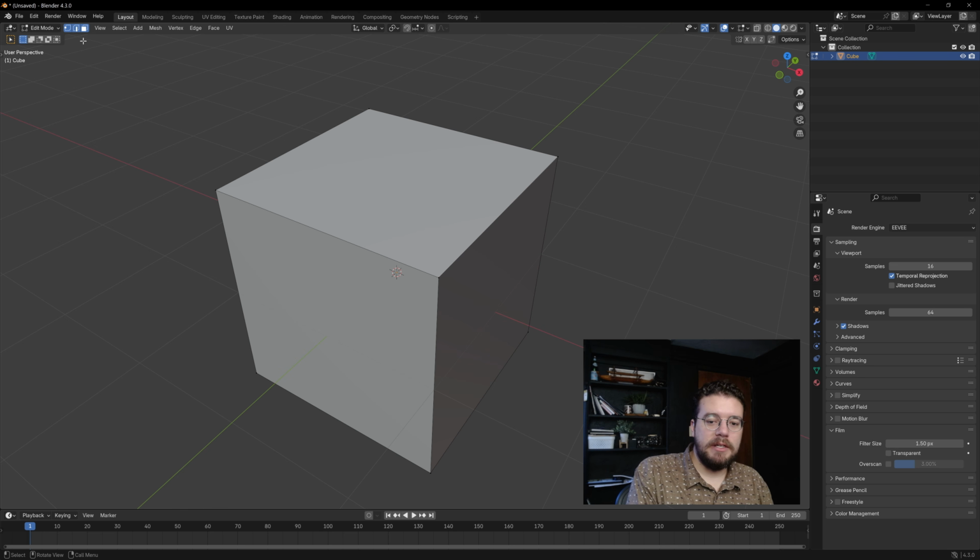If you look at these, you can even hold down Shift and have a few of them selected at once. Let's go to point mode first, and we can click on these various points, and you see that they're highlighted and selected. We can hold down Shift, and we can select a few of them. Next, we have edges. Same principle, but now it's just the edges in this cube. And then, of course, we have faces where we could just select the faces.